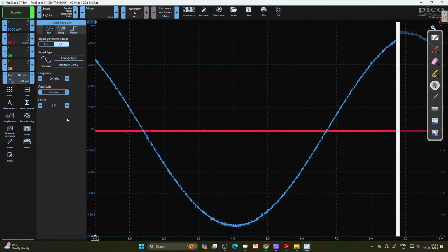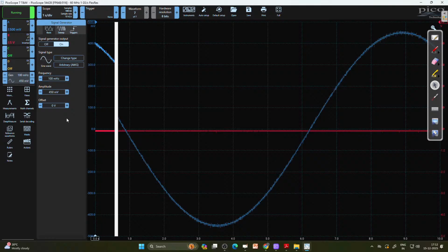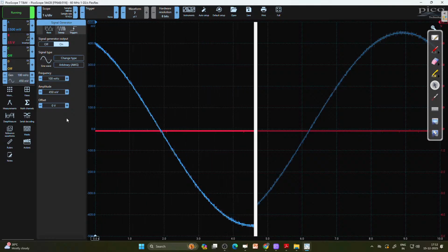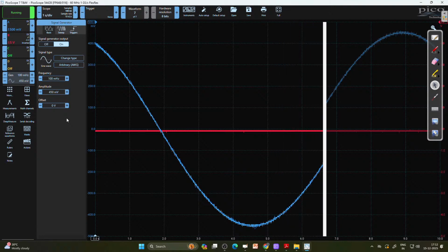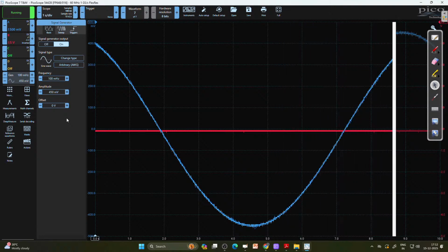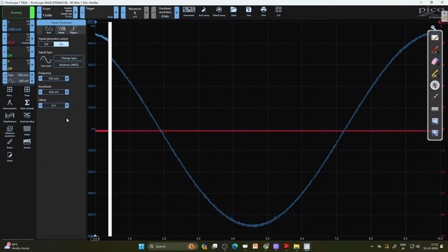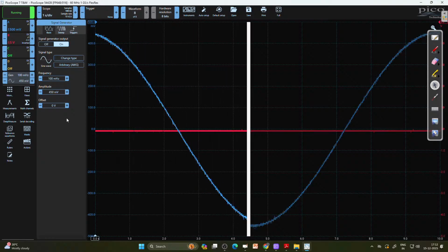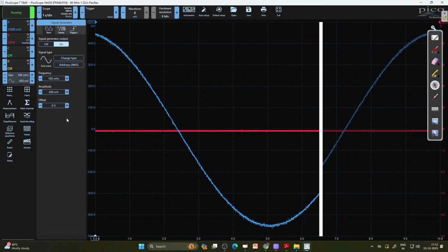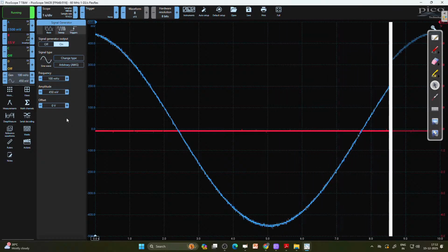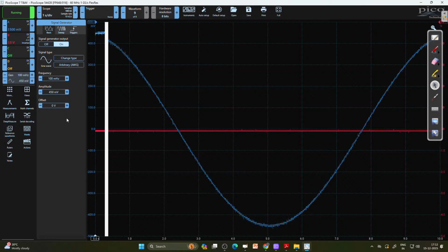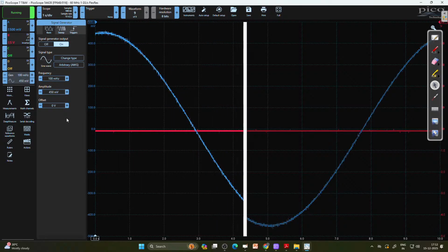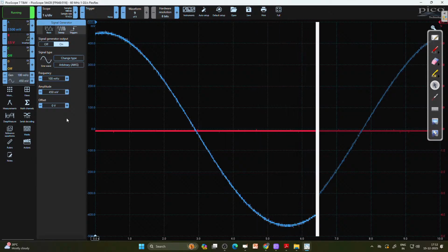And the high voltage amplifier has an amplification of factor 200. So from 0.45 volts, I get 90 volts. So now I go between plus 90 volts and minus 90 volts. And since the distance of the electrodes is very small, far below 100 micrometers, this is a field above 2 kilovolts per millimeter, which was your question.